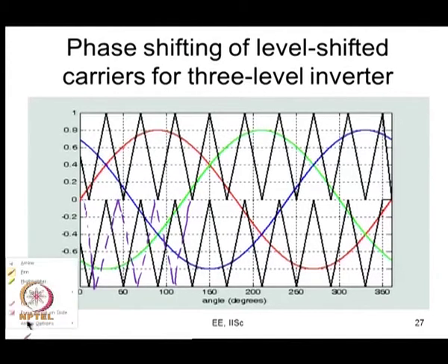So, what would be the effect of doing this now? So, you see that this is at some phase, this is at some other phase, maybe phase shifted by 20 degree or 30 degree at the carrier frequency. This will not affect the fundamental, but this will impact the harmonics. So, sometimes the harmonics may change for better and many times it may change for worse.